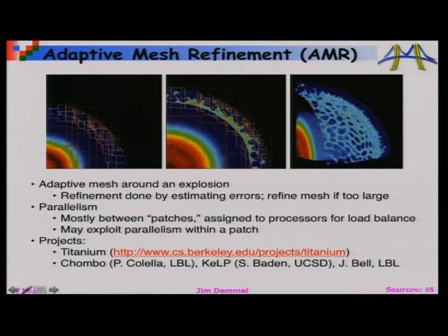So you have to have a very, very fine mesh where you're solving your equations out here. And you have to resolve that finely because the chemistry is complicated. Out here, you don't need to spend much time computing because it's nice and smooth. And so what you have to do is change your mesh dynamically over time as it moves. This makes things even more challenging, and there's lots of projects where people have actually done this and parallelized it using the tools that I've told you about and will be telling you more about tomorrow.